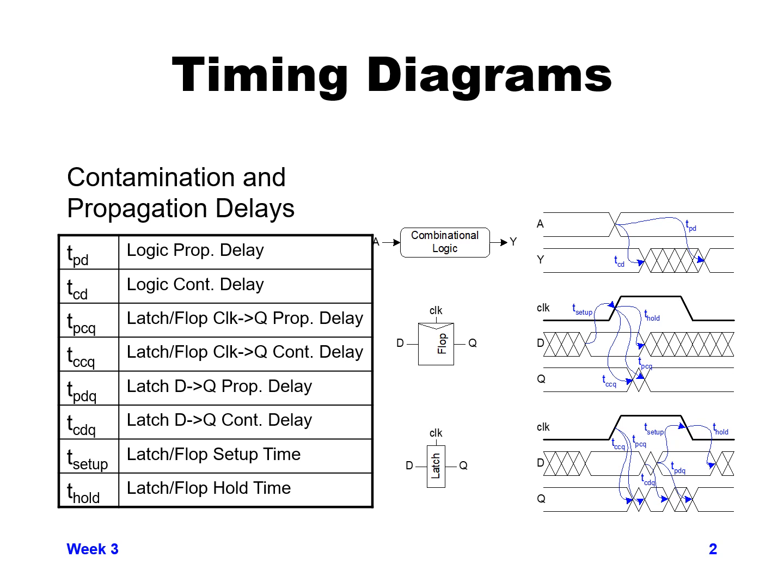Now that basically relies on D being stable at the time that you're sampling it. So there's something called the setup time, T setup, where the last time D changes has to be a certain amount of time before you try sampling it, and it has to stay stable while the clock is rising, because otherwise you'll get some unknown value.